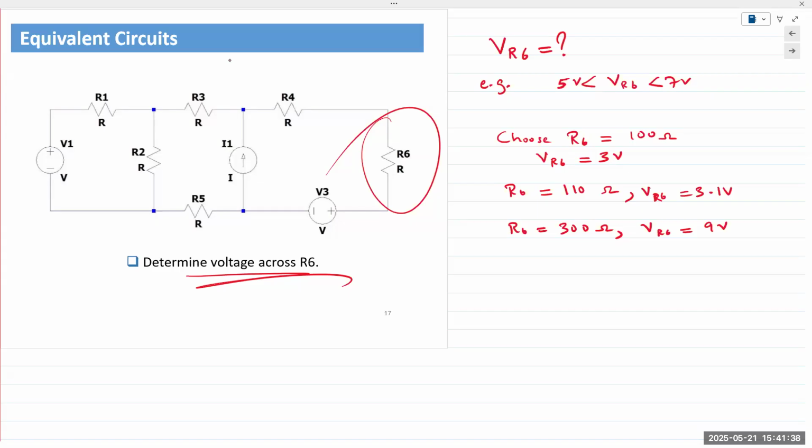Well, in order to not do that, there was a French telegraph engineer. His name was Leon Charles Thevenin, way back in the late 1800s. I believe he was an honorary commandant in the French army, and he postulated a theory. He said, if you have a linear circuit comprising only linear elements like resistors, and you have independent sources in there, you could represent that entire circuit with one single voltage source and one single resistance.